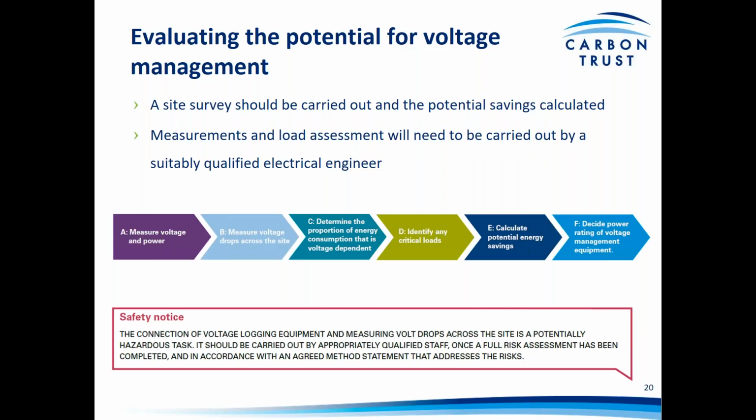So they would be to measure the voltage and power, first of all, to measure the voltage drop across the site, to determine the proportion of energy consumption that is voltage dependent, to identify any critical loads that you have, to then calculate the potential energy savings that could be achieved, and finally to decide the power rating of any voltage management equipment that you would be looking to install.